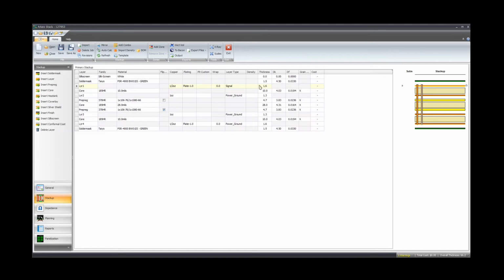So, half ounce copper. The impedance design may specify they want to use FR4 material on the stack up, and NetVia's default selection for FR4 materials is Isola's high reliability 185 HR. Whenever we use that, they have their own dielectric constant requirements that play a factor in the impedance calculation. So this model knows of the Isola 185 HR dielectric constants.